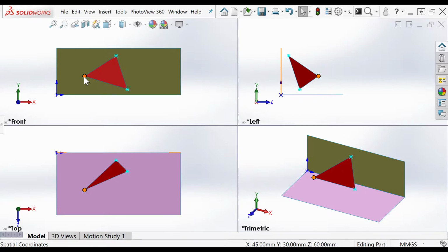The same thing applies to B. So point B is the top one, is this one up here. So B has an x value of 96. It has a y value of 63, so it's 63 millimeters up off the ground, and it has a z value of 12, so it's 12 millimeters out from the vertical plane, which we can see in the top right corner of our screen. And then C, we're also given the coordinates for that.